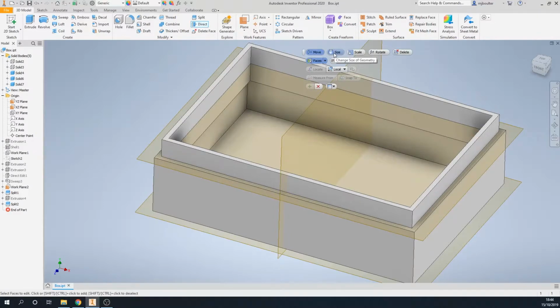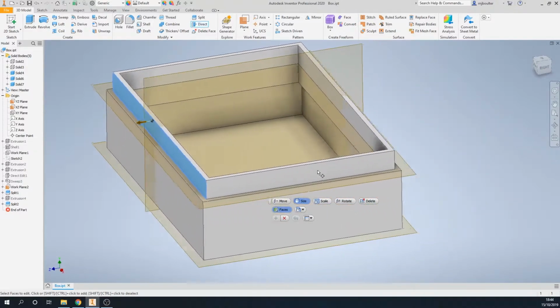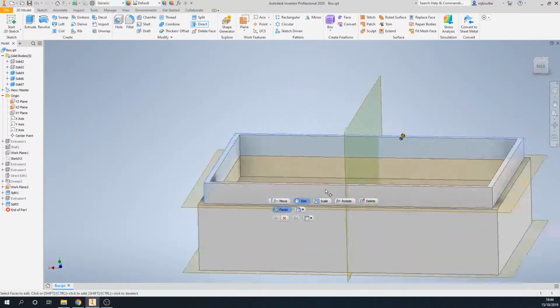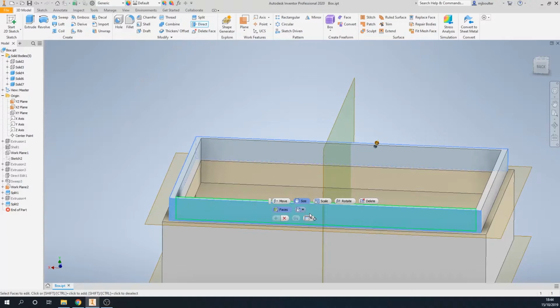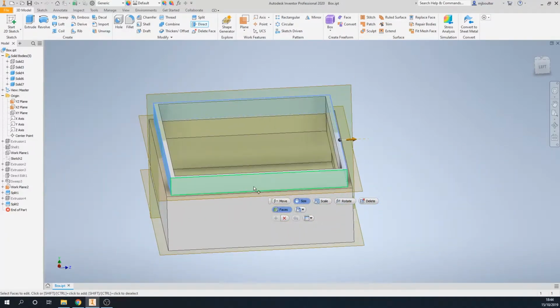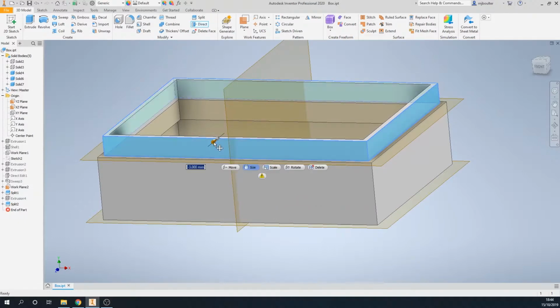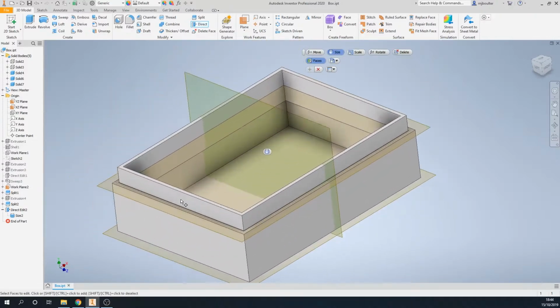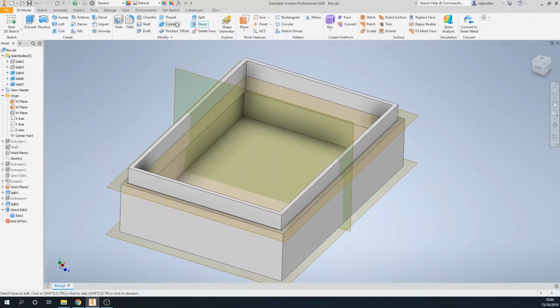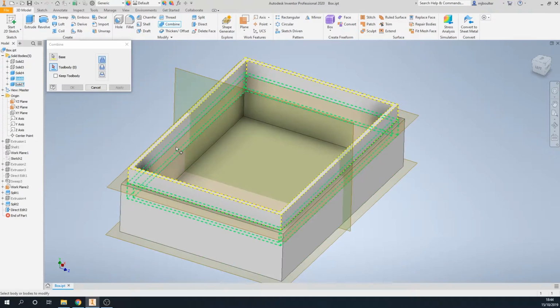First off, I'm going to direct the size of the dimensions of this top flange in by 0.2 of a mil, so it gives a bit of clearance so that they fit together better. So I'll push the golden arrow back a little bit, type in -0.2, click OK, and now we can combine all of these solids together: top, bottom of the flange and the bottom of the box.